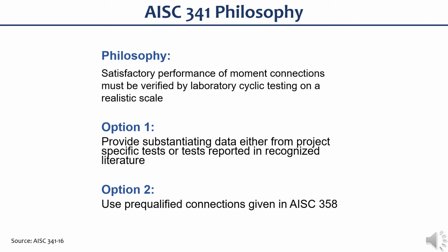The behavior of SMF connections, especially the initiation and propagation of fracture, under severe cyclic loading cannot be reliably predicted by analytical investigation alone. Therefore, AISC 341 adopted a philosophy that performance of moment connections must be verified by laboratory cyclic testing on a realistic scale.